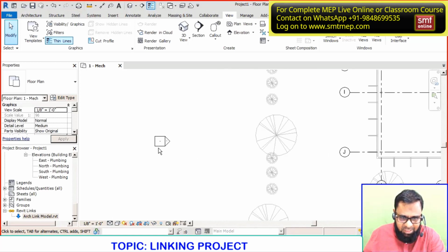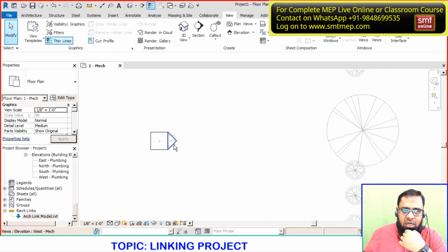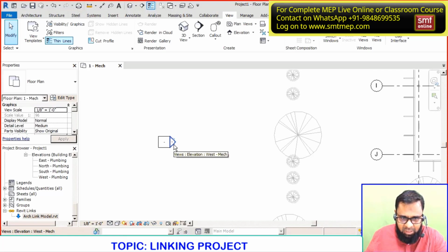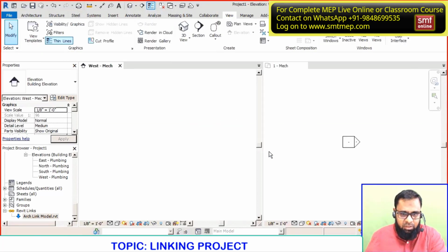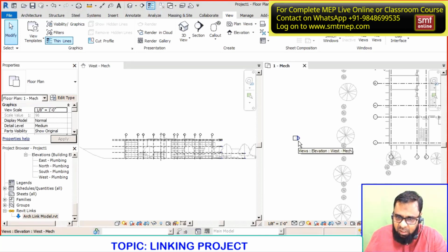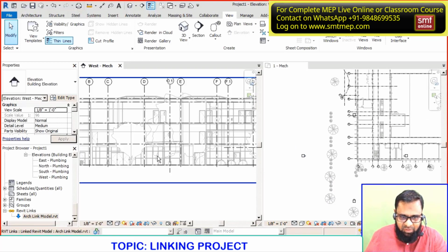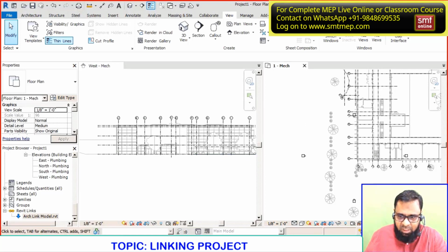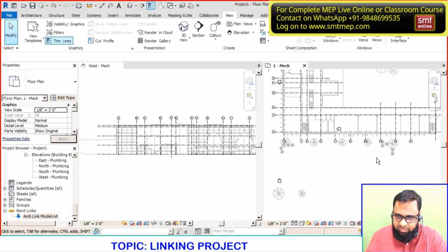So first camera, select this square. You see we have the option, when you double click this triangle on this elevation camera, let me show you what will happen. The elevation view will open, you see, and type WT, tile window. Left side is elevation, right side is plan. So just now I double clicked this side elevation, which means you are standing here and seeing this side, and this side view is available here. Similarly, if I double click this triangle, on this side, you can find the elevation of this side. I think you're getting my point, right?